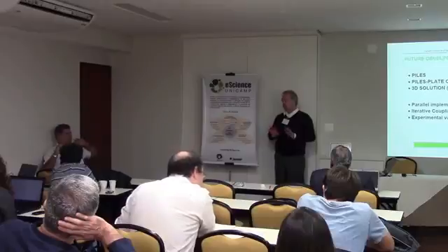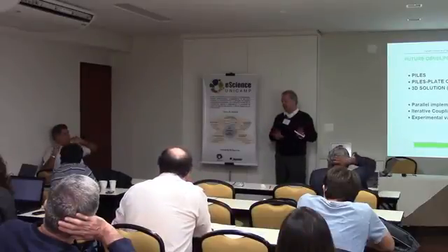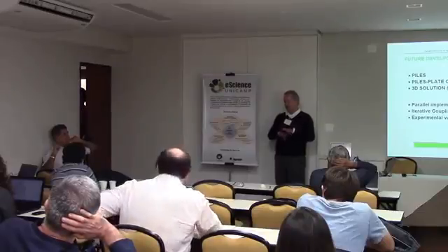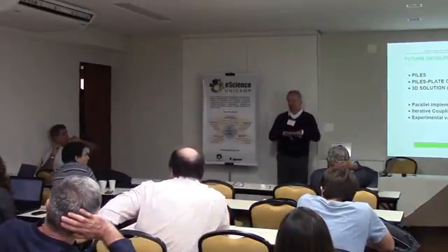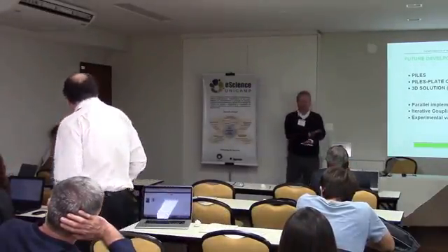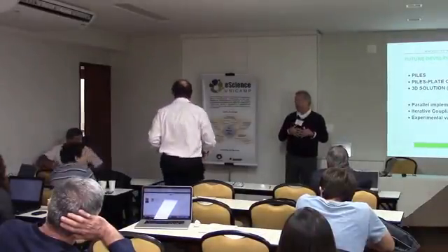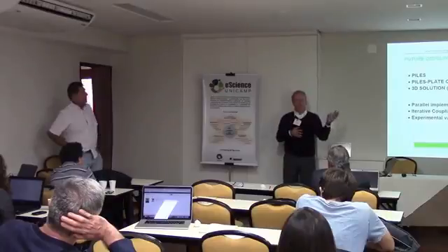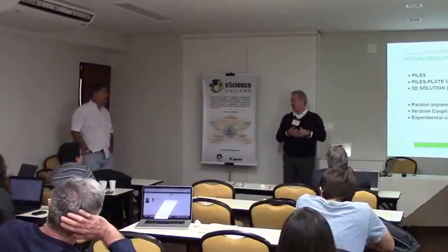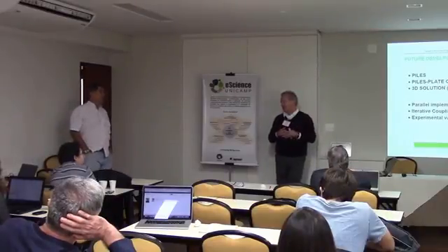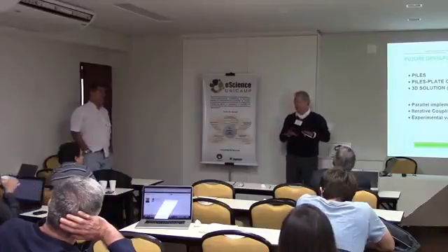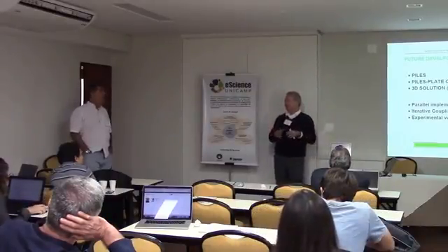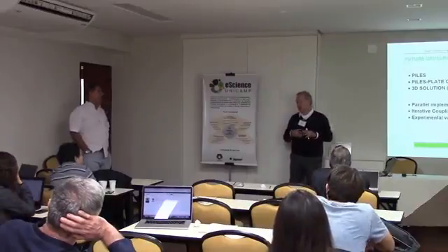There are two dissipative mechanisms in a system like this, provided that you assume bonded contact and you forget about friction and things. One is internal material damping from the soil, which is a viscoelastic solution. The same thing can be said about the plate. The other is energy carried away in the form of waves that are not reflected back to the system, which is called geometric damping.